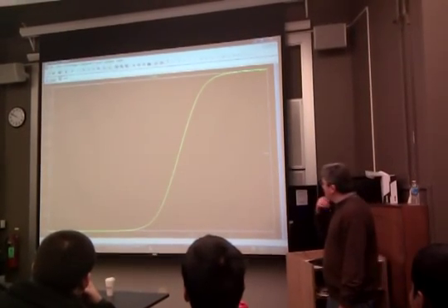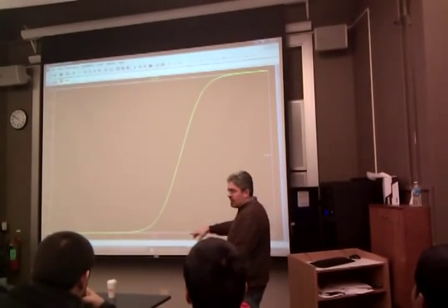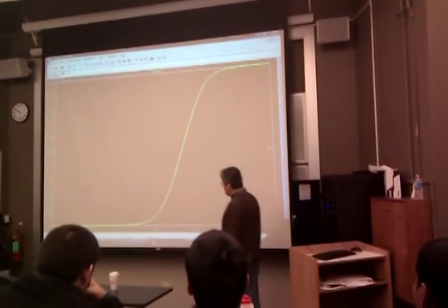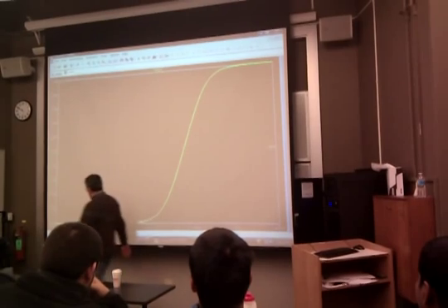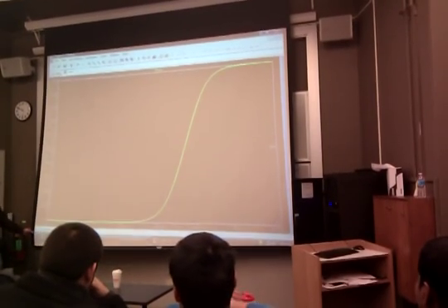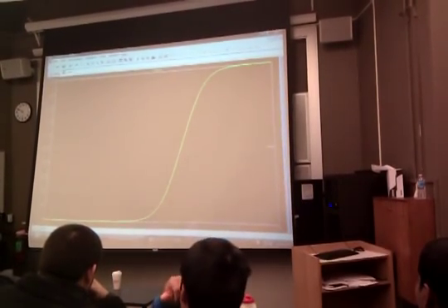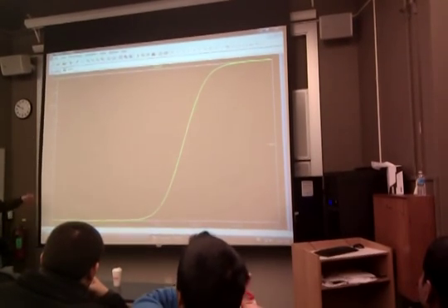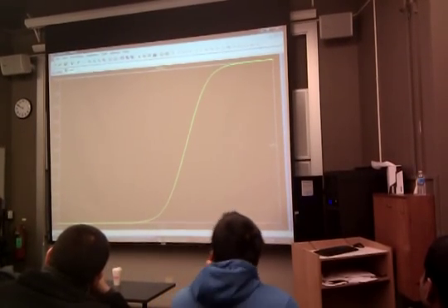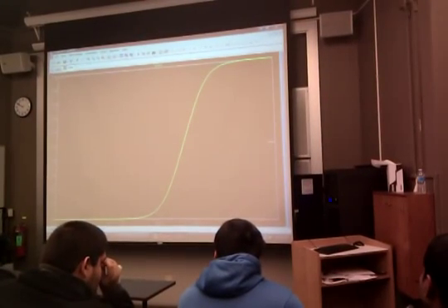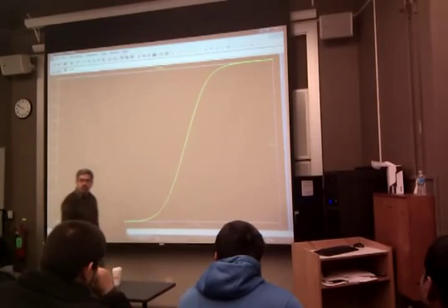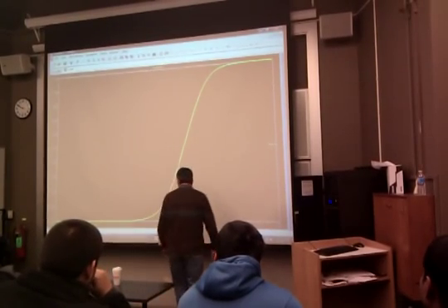So this kind of looks like, I mean, forget about the frequency points, right? But it does have that shape. It's minus 20 dB here. There's a minus sign here, right? And the high frequency gain is 0 dB. We kind of knew that, right? Because the factor out front, remember on the passive one was like C1 over P1 for that RC circuit. And that is actually what we expect.